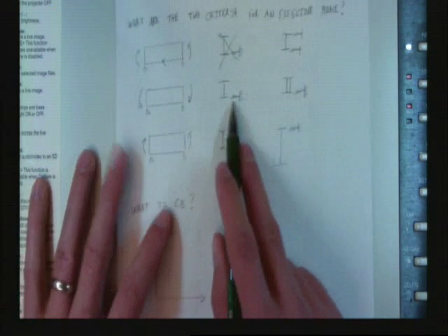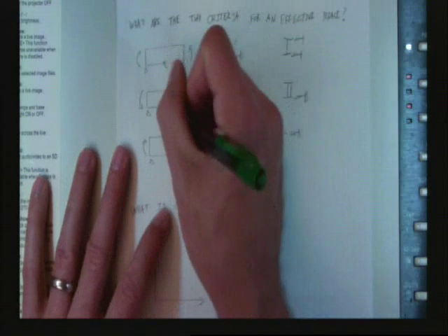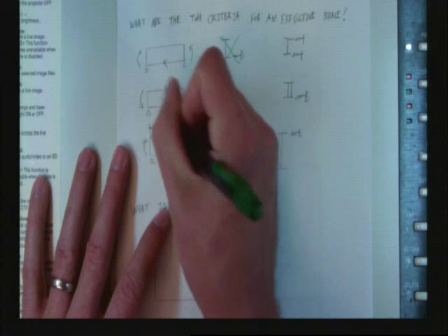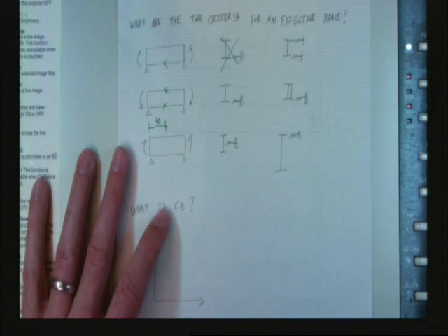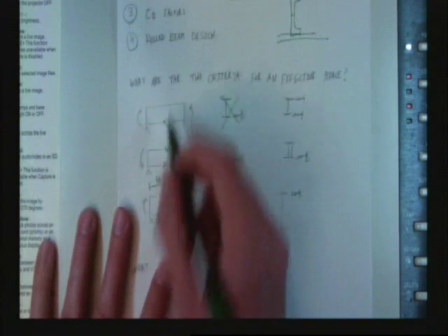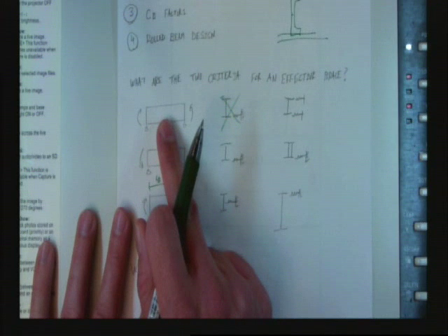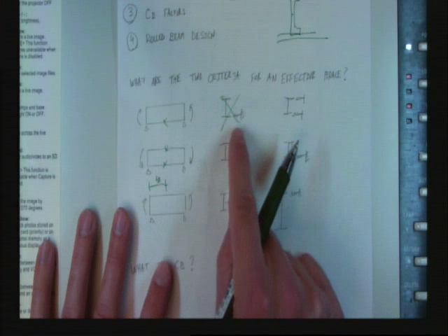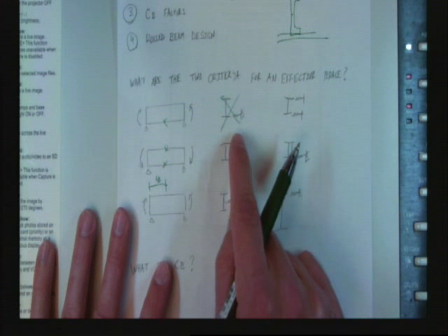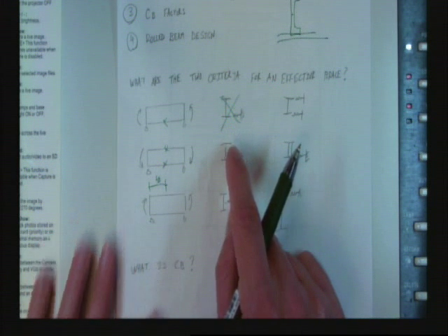So when something's an effective brace, then you could actually assume that the L sub B was that distance, right? If it's not an effective brace, you ignore the stiffener. Hopefully, if you're designing, you don't use braces like that. You understand the system, and you go from there.